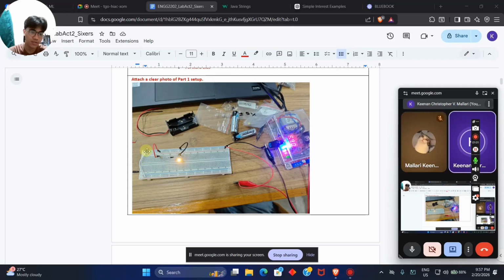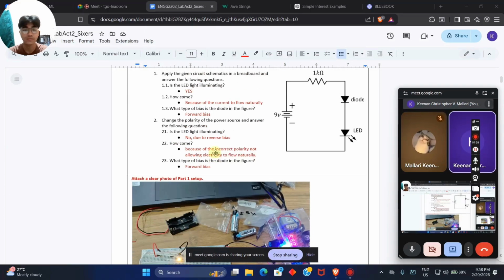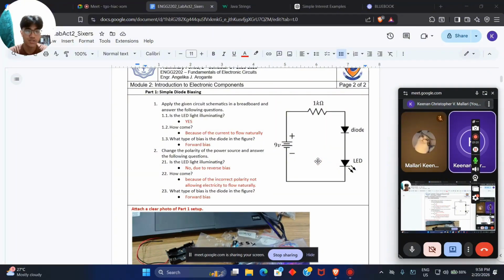Here we place the corresponding wires to their positive and negative inputs, putting the right wiring components such as the resistor, the 1N4001 diode, a yellow LED, another wire, and just connecting the power supply to the breadboard itself. Now let's answer the questions.